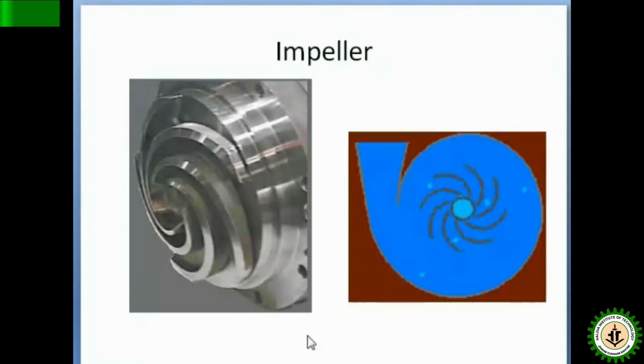One principle I said is the in and out part: axially in, radially out. Second, as I said, it should be a backward vane design to act as a pump. For a pump it is the same, and for a blower it is also the same. A fan is a flat blade type, so it doesn't matter which direction it rotates. But for blower, compressor and pump, these are mostly the same, because apart from compressible and non-compressible fluid, the concept is more or less the same.